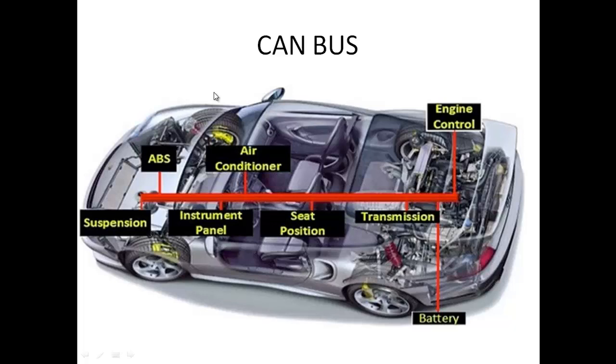In olden days when you pressed the brake, it would suddenly apply and bring the wheels to zero movement, but the car would not stop; rather it would slide. All four wheels are at rest, but you have come at 60 or 80 kilometers per hour, so rather than stopping, it starts sliding. In ABS, you apply the brake in a pulsating manner: apply, release, repeatedly, so that the speed is brought to zero and your car will not slide.